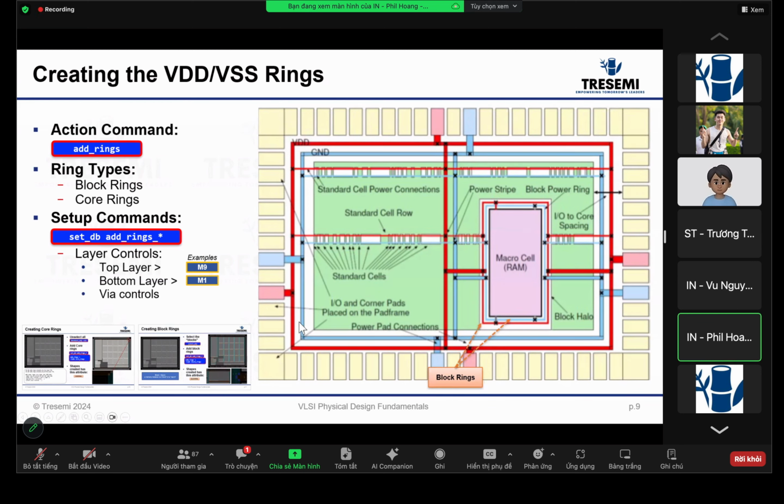this ring. Khánh Dương, is it possible if multi-voltage domains are routed on the same metal layers? Oh, absolutely, yes, as long as they are not shorted together. So yeah, they are different voltages, but they can be in the same layer, as long as they don't touch each other, creating a short.